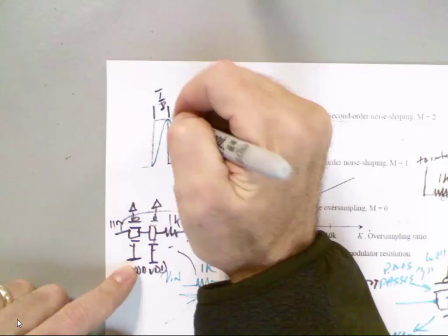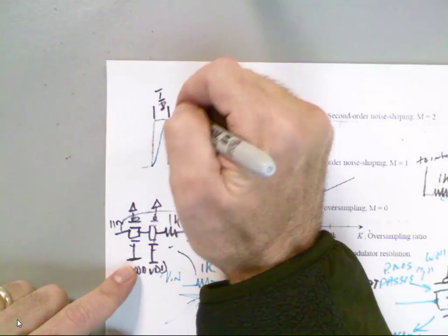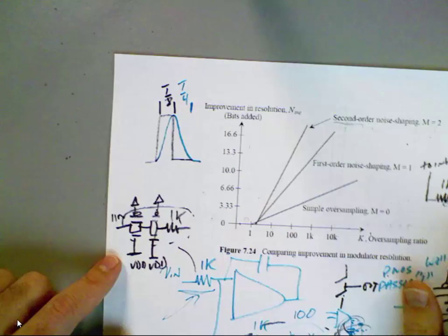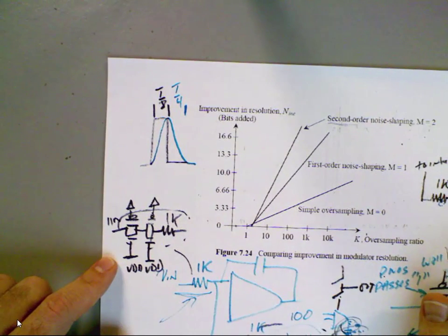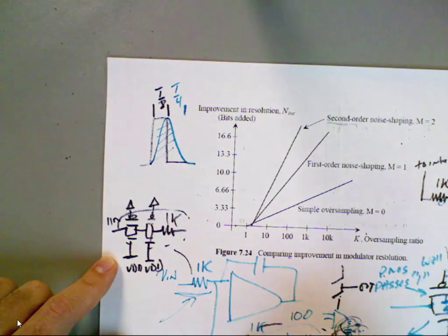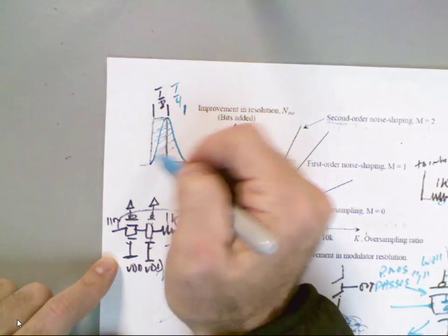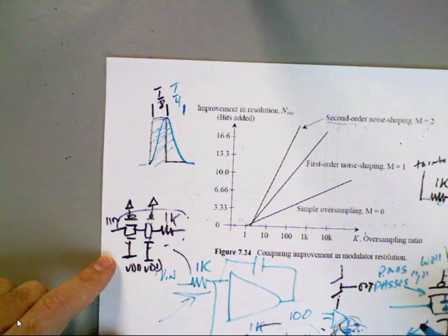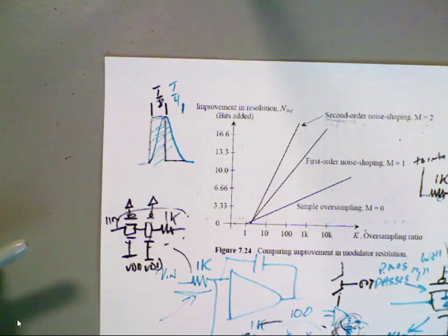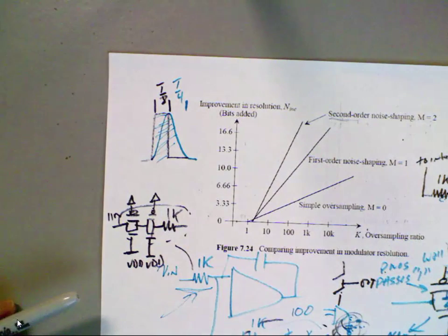And then this is from here to here, or maybe you could draw it as T/4, T/6 if you adjust the clock phases, right? Well, this amount of charge that flows, and you have to look through here, is the same as what you get in this. And so it ends up being equivalent to clocking with the faster clocks, but because you can't turn the devices on in 1 picosecond, you get this slower turn on.